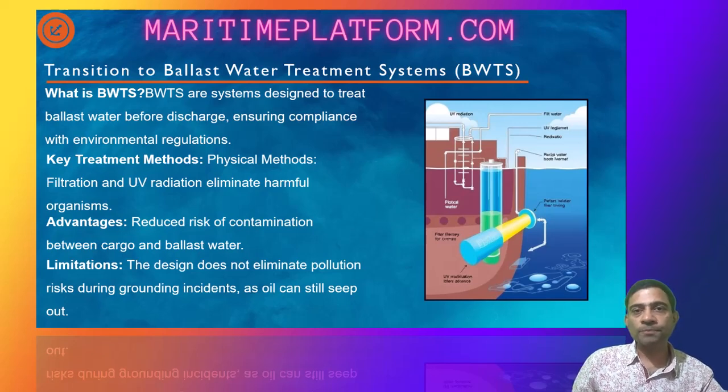So it is not an advancement to double hull tankers where you can say the ballast water treatment system will prevent all kinds of pollution, including oil and microorganisms. It is just a system in line of the discharge system where it will only cater to the organisms, which will be nullified before the ballast water is discharged to sea.